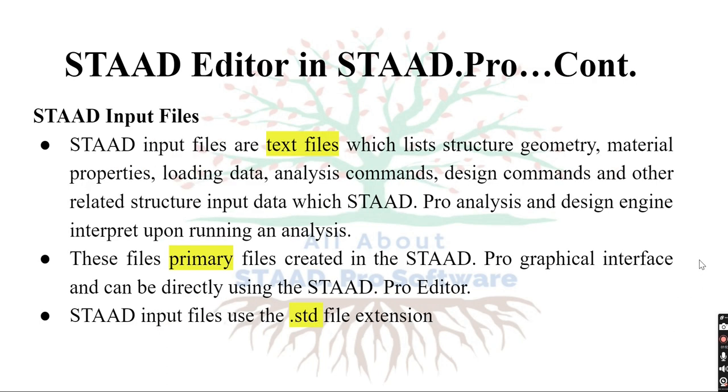STAAD input files. Let's see what the input files are and what they contain. STAAD input files are text files which list structure geometry, material properties, loading data, analysis commands, design commands and other related structure input data which the STAAD Pro analysis and design engines interpret upon running an analysis.